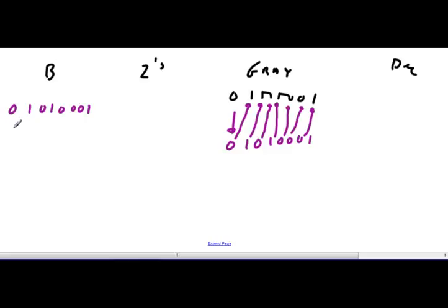And then I'm going to find 2's complement, so 1, 0, 1, 0, 1, 1, 1, 0. So the 2's complement answer is going to be 1, 0, 1, 0, 1, 1, 1, 1, because I added 1 to this guy. And now I'm looking for the decimal: unit, 2, 4, 8, 16, 32, 64. So I've got a 64, a 16, and a 1. So that looks like an 81. All right, next one. I've got a 45 decimal.